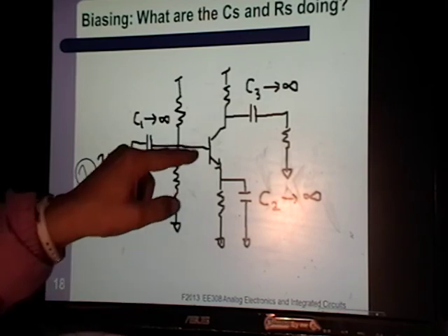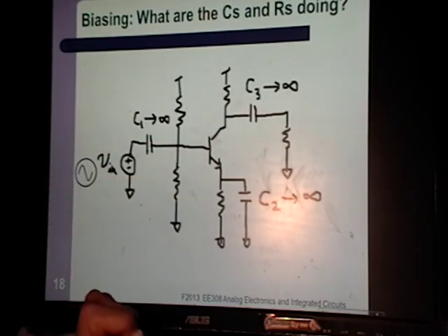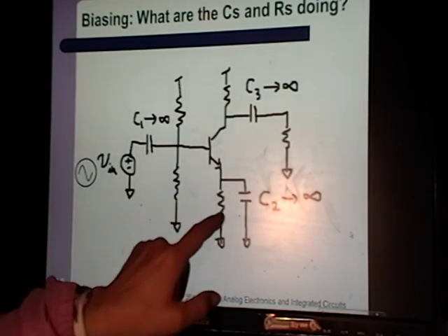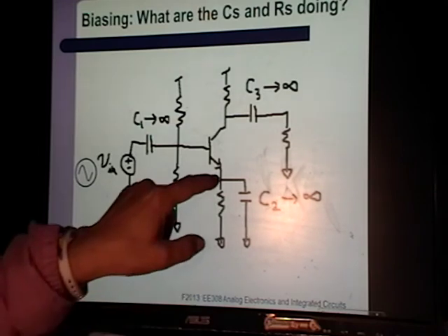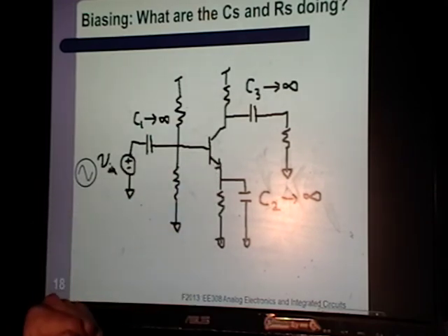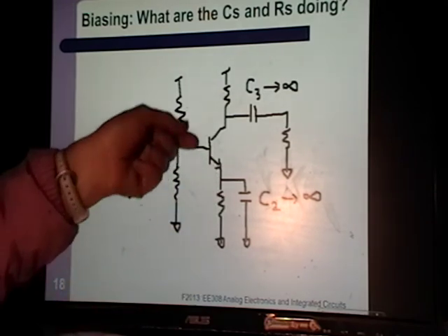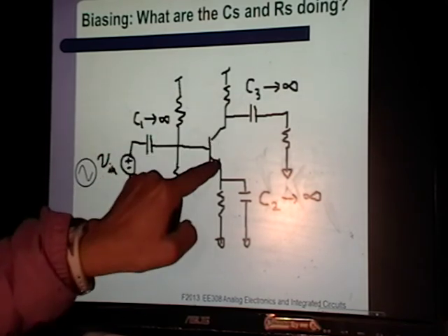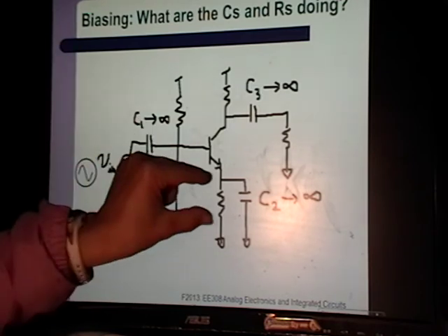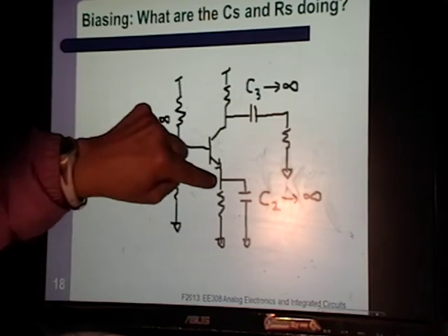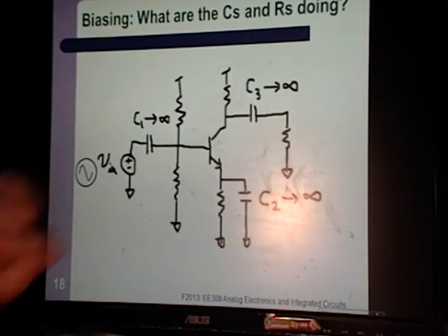When you change the base voltage, you get a current change through this transistor. If that current change went through the resistor right here, this node would move around. And remember, this is a biasing resistor, so it's trying to set a voltage here. So you don't want that to move.